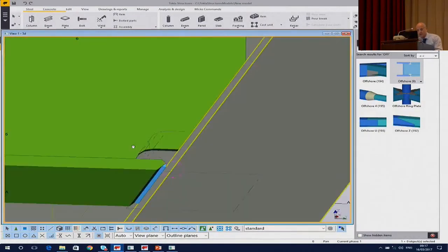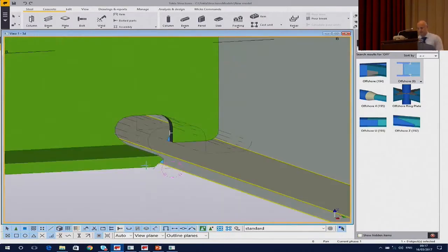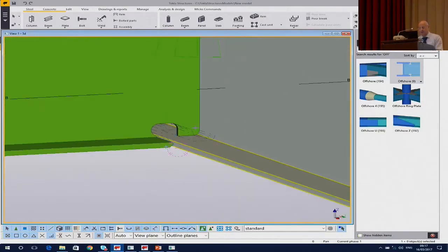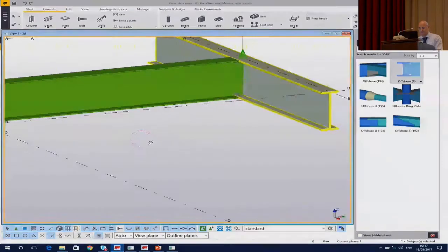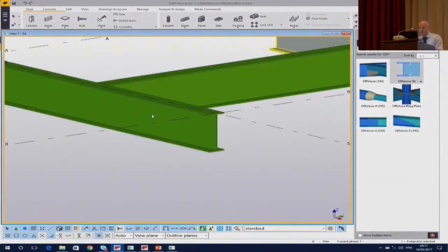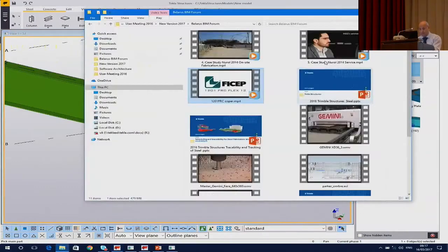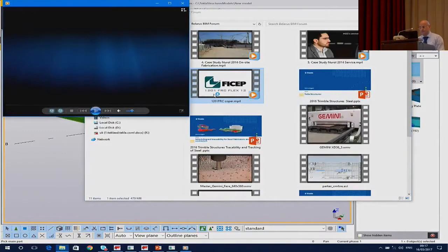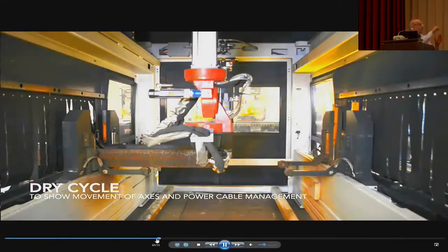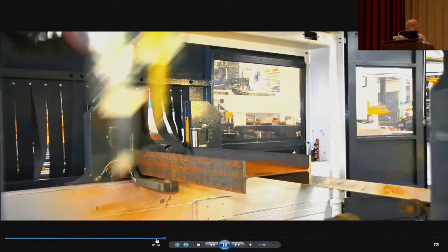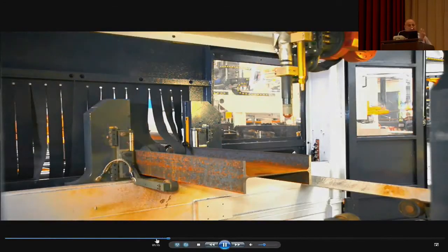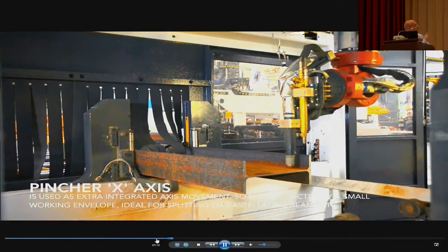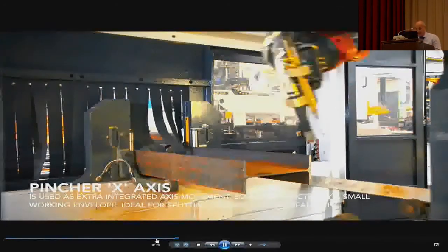So you can see there, look, the weld preparations, they're called mouse holes, and all the way through like so. Even for something as complex as this, we can download that directly to the V-shaped machines. Let me just give you a little look at the example of that. Let me just expand this out. So these are now automatic coping robots. You can see here then that the information for all the weld preparation and everything is all the way down from the Tekla model.